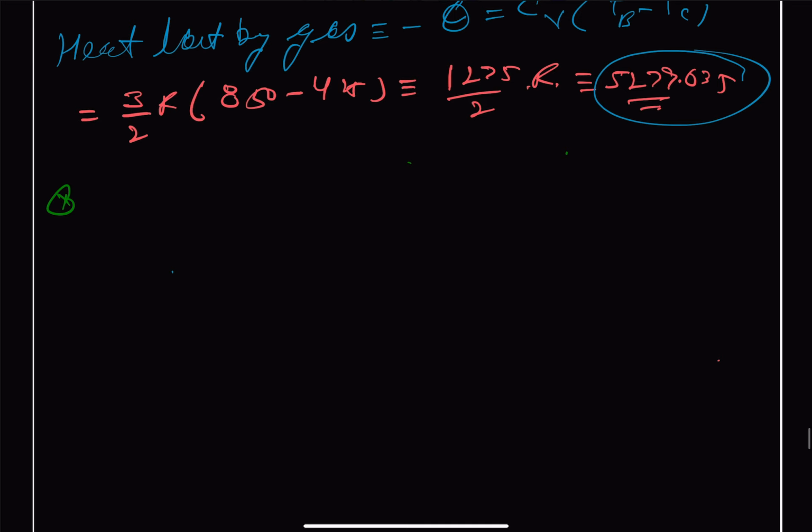So we start with path AB. We are going to deal with this from the temperature point of view because then it will be easier to substitute. Okay. So we can say for path AB, we can write this as PA to the power gamma minus 1, TA to the power minus gamma is equal to PB to the power gamma minus 1 and TB to the power minus gamma.